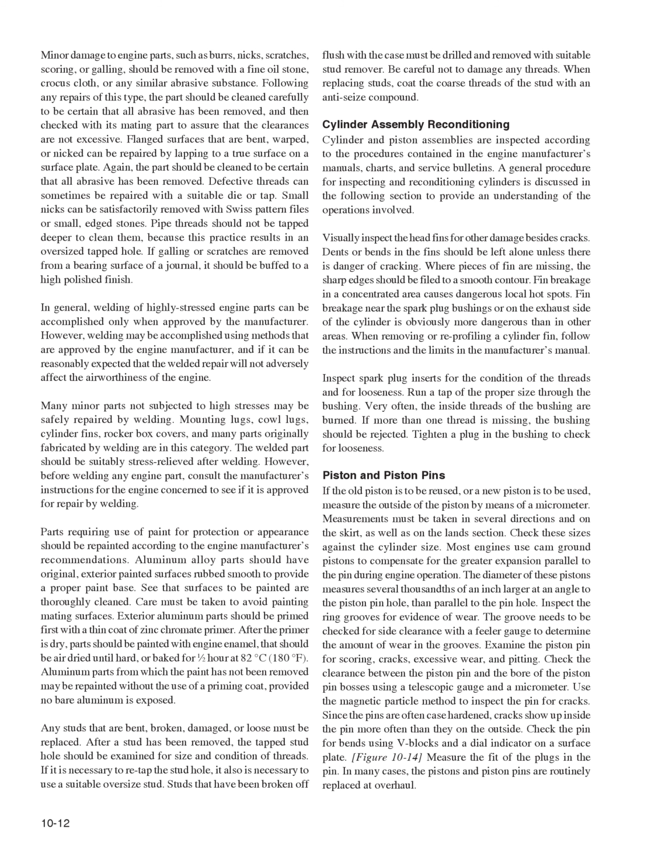Inspect spark plug inserts for the condition of the threads and for looseness. Run a tap of the proper size through the bushing. Very often, the inside threads of the bushing are burned. If more than one thread is missing, the bushing should be rejected. Tighten a plug in the bushing to check for looseness.